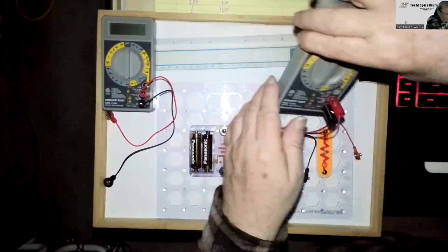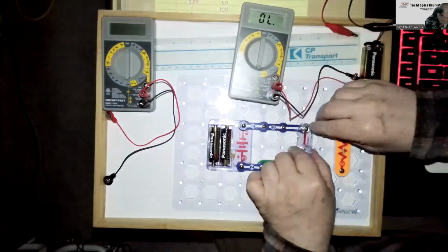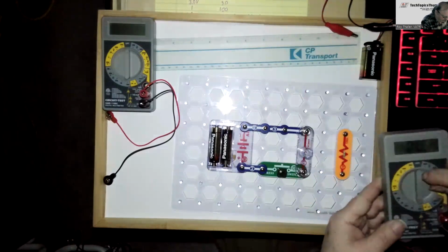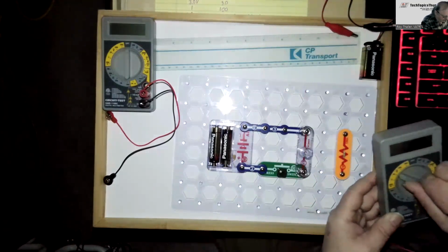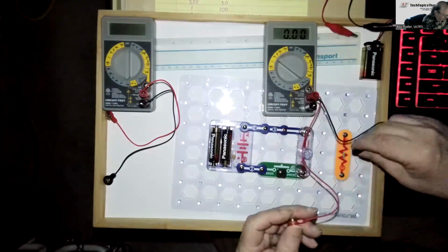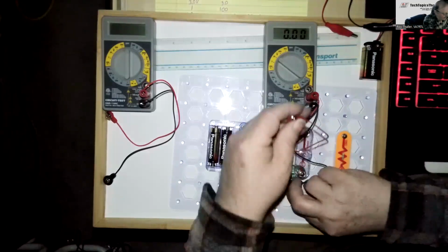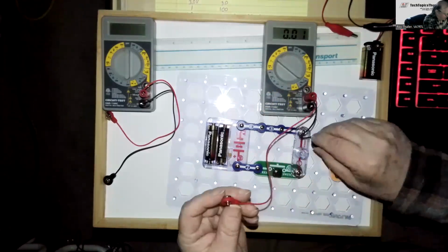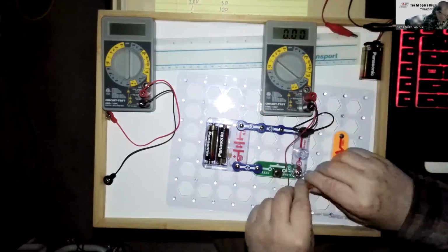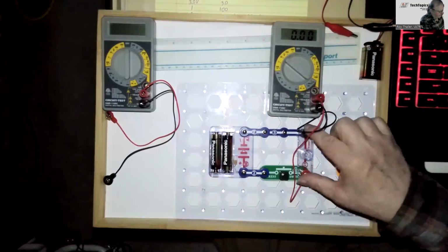and what I'm going to do here now is switch this over to volts. So I'll turn the multimeter over to volts. So I'll turn it to a 20 volt scale, and then I'll connect this. It doesn't really matter how you connect it. If you connect it the opposite way, it'll tell you that you've got the things reversed by having a minus sign on it. So voltage is connected across the resistor.